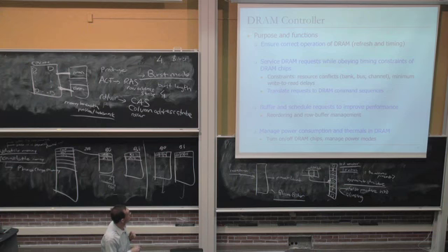It also has other duties today especially. It needs to manage the power consumption and thermals in DRAM. So many memory controllers turn on and off DRAM chips or manage power modes to minimize the power in DRAM. You can think of this as many cores, many controllers for processors changing the power modes of the processor, changing the voltage and frequency.